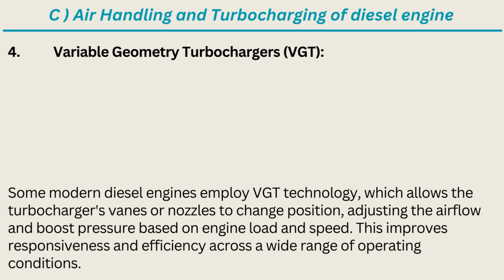4. Variable geometry turbochargers, VGT. Some modern diesel engines employ VGT technology, which allows the turbocharger's vanes or nozzles to change position, adjusting the airflow and boost pressure based on engine load and speed. This improves responsiveness and efficiency across a wide range of operating conditions.